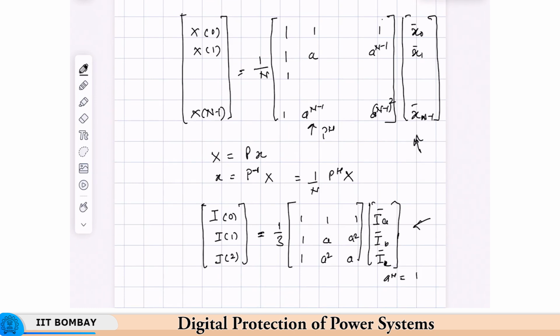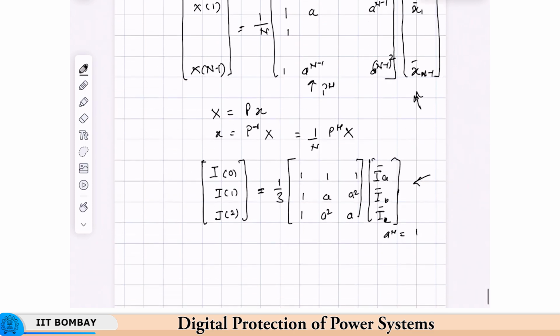Now, as we can see, mathematically they are the same, though application wise they are different. We don't look at it that way because we don't develop the properties of the sequence transforms the way that we develop the properties of the DFT, like phase shifting and symmetry and superposition and other properties that we discussed in the last few lectures.